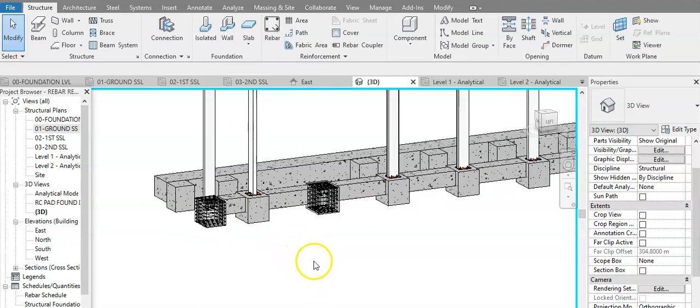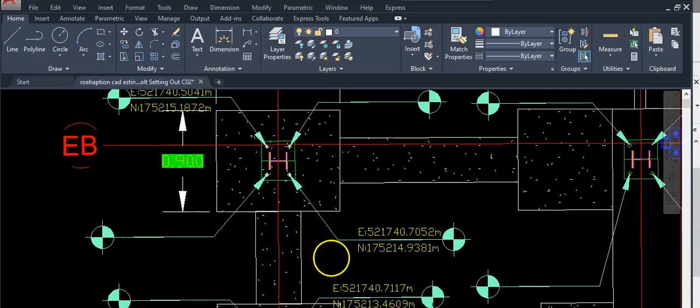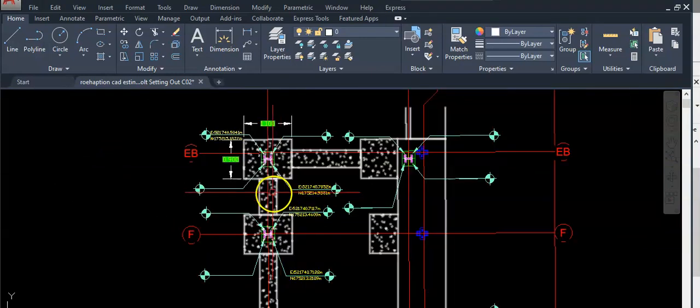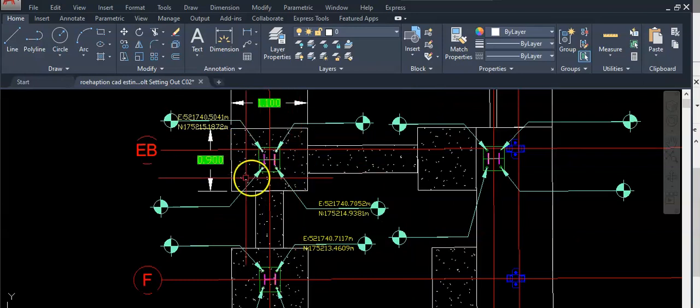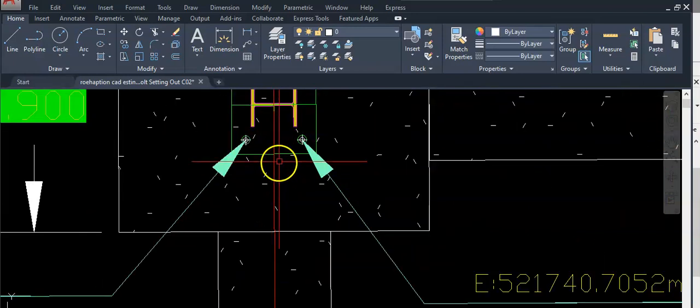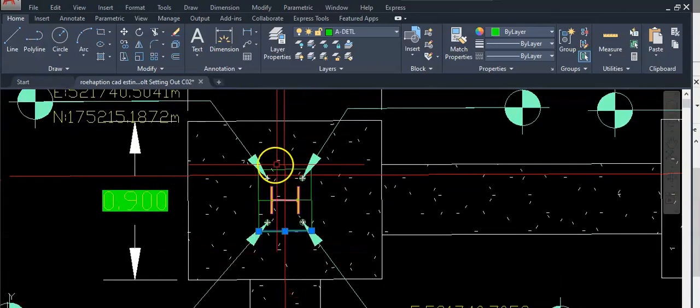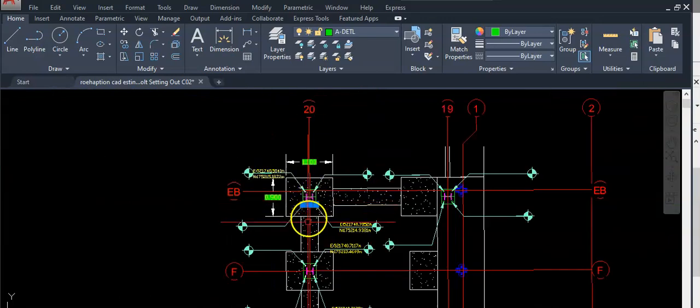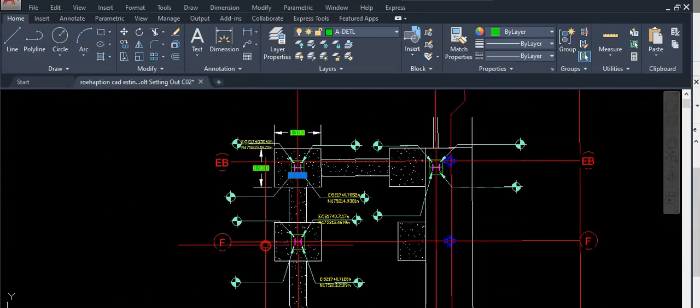But when the project is given to the operator on site, it will come with a drawing like this one, which is exactly the same as the model which has been converted. What we see here is the pad foundation as the 3D model, this shape there represents the green holding down bolts, and this H shape there is the columns themselves.